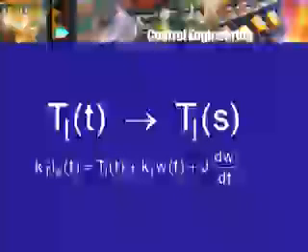No, that is not the equation. The equation starts with the generated torque. What was the generated torque? K_T into I_A. This is the torque produced by the motor because of the motion of the conductors carrying current in a magnetic field. K_T into I_A equal to, there are two terms earlier. What are the two terms? One was the load torque, of course, T_L(t), plus the torque to overcome friction, which was K_f into omega. But now, because the speed may be changing, I have to consider the moment of inertia term, and I told you the moment of inertia is usually denoted by J. So, I have J into d omega/dt. So, now there is a derivative appearing in this equation also, like the armature equation.